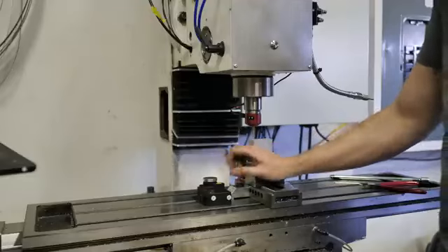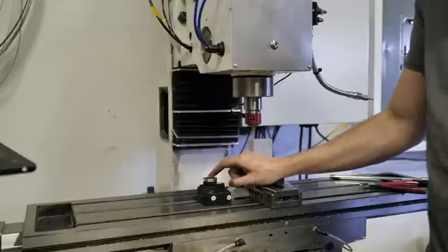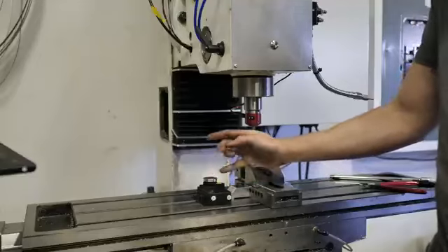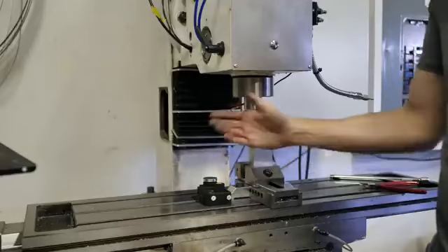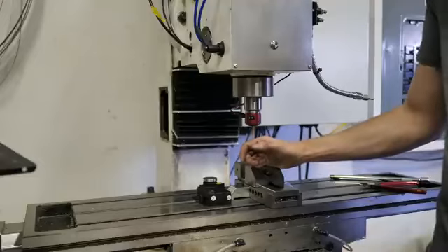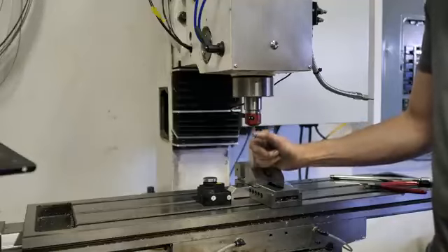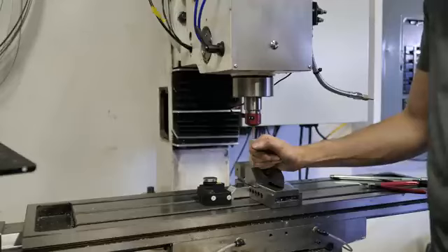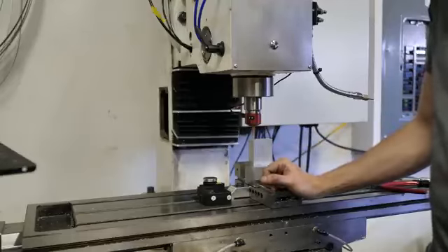And that'll come down and probe it the same way it probes Z, except instead of telling the machine it's at 0 on the Z axis, it figures out the difference between that Z0 and what it just measured and spits that out as the tool height. And it will automatically populate your tool table with whatever tool you have selected and that tool height. So it's pretty automatic. I can run through 24 tools in 5 or 10 minutes. Pretty handy. Other than that stupid thing where I've got to change the pin number on the probe.